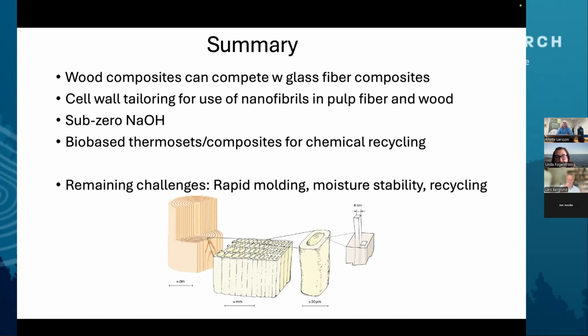Can I just comment? Regarding your first comment, Jan, Lars, isn't it so that the work by Peter Rosén, which is really interesting, is one way that you manage the molecular weight problem versus viscosity, at least to get the polymer into the matrix, by having it branched? Then you have a higher molecular weight and still have quite low viscosity. So there are ways to manage that also. Yes. I think that was a really nice way to do it.